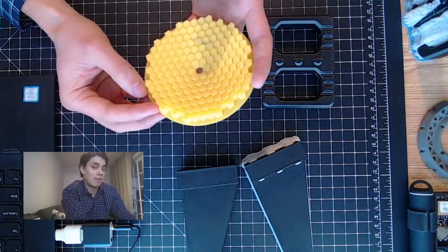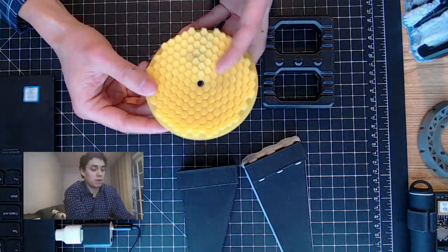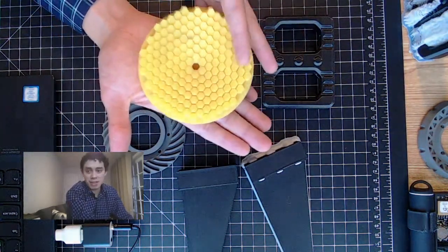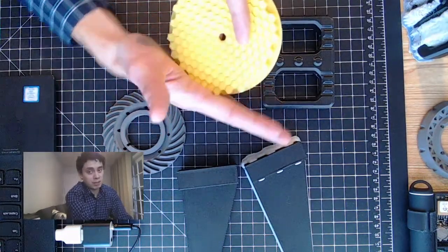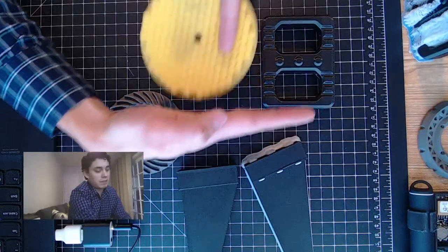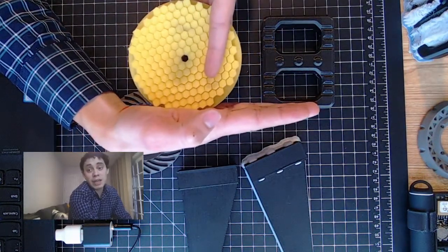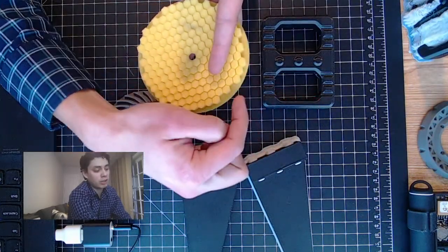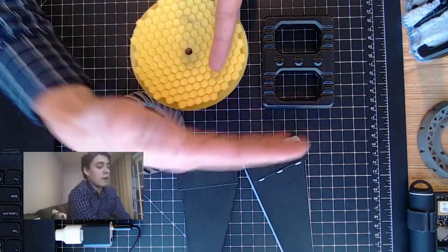But I still have the other two considerations, which are how changing the orientation of my part will affect the supports that I'm using, right? If I'm printing it flat like so, it didn't require any supports. If I was to print it sideways, or actually standing up on the build plate, I would probably need supports just to make sure that it's not wobbling around, especially on these outer edges of the circle, to make sure that I have something to print on.